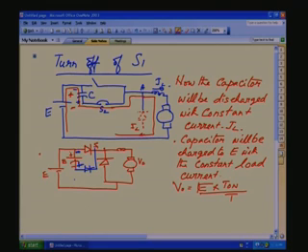For a circuit, the load current can vary. If the load current is maximum, the capacitor discharge will be fast. So even for the maximum load current, the discharge time should be more than the T off minimum of the thyristor.